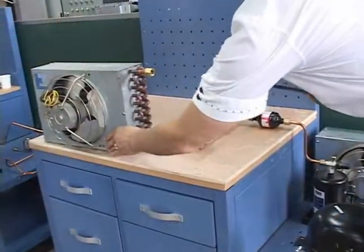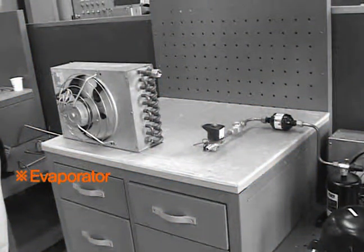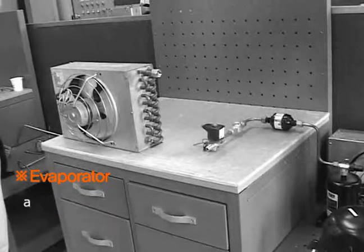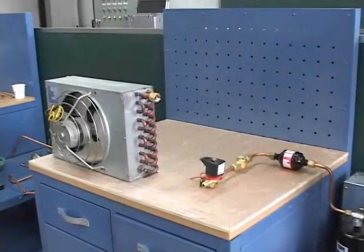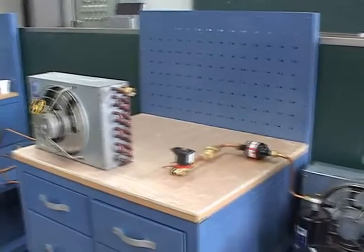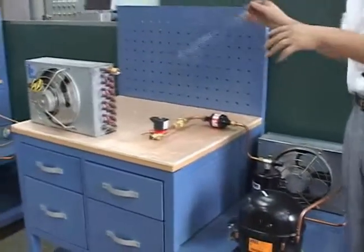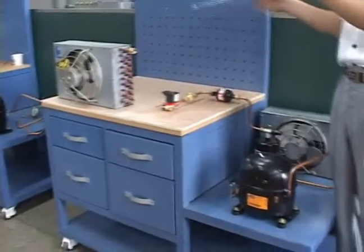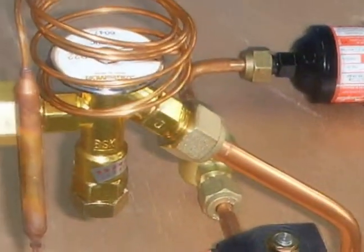Now we will fix the evaporator on the table. The evaporator takes the low-temperature, low-pressure refrigerant liquid from the expansion valve and cools or refrigerates it. There are air cooling type and water cooling type evaporators. The evaporator takes the low-temperature, low-pressure wet vapor or low-temperature, low-pressure refrigerant liquid from the expansion valve and exchanges heat with the air. The refrigerant goes into the compressor after it has been changed into gas state by removing the external heat.